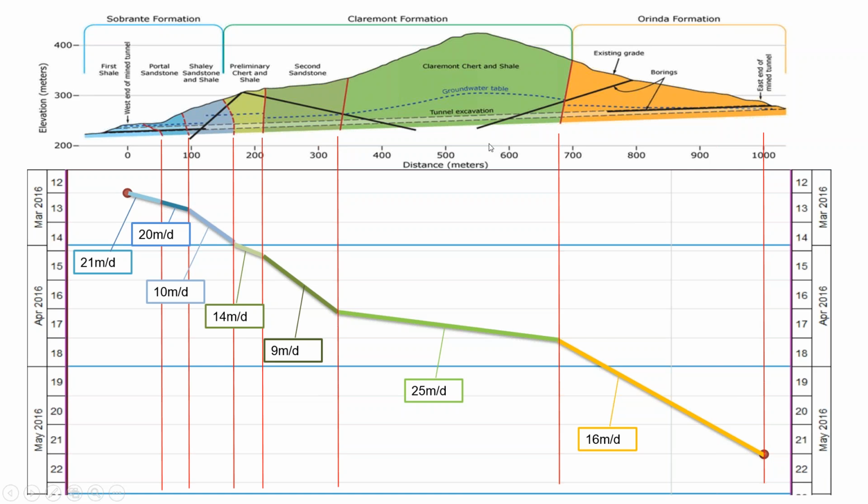This is very important because the TBM machine and the day is a driving factor of cost in tunnel projects. If we have a very difficult area, whether we make 20 meters per day or 25 meters per day, it impacts our project duration. And if we are renting the TBM, usage of the TBM is a direct cost for our projects. So soil class is one of the factors impacting our project cost.